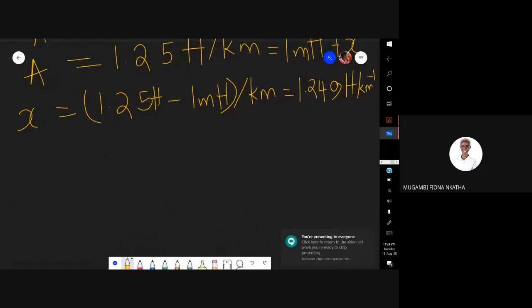So calculate the percentage change in phase velocity as a result of the loading. From the equations Gisheru took us through, we saw that phase velocity is equal to 1 over root LC, and we have the old L and the new L. So let us call this the old.